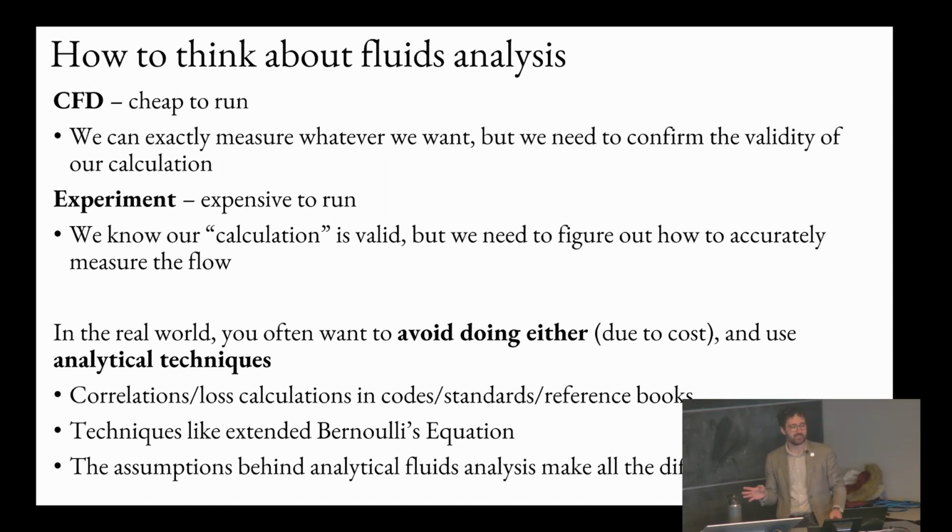I want to close the course by talking, from a bird's eye view, about what we should think about when we do fluids. You have three options. You can avoid doing either CFD or experiment, which is almost always the best option due to cost. CFD is cheap to run, experiment is expensive to run, but they have the inverse problem. In CFD, you can know whatever information you want because your fields are all stored on your computer, to perfect precision. But because of the models, you don't know that you actually have a valid solution.